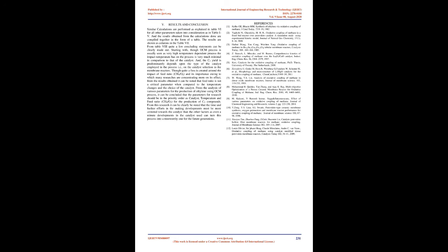Table 1, analysis table for membrane reactor at normal varying temperatures. For statistical analysis calculations, the factorial design technique is now applied on tables 1 to 5 to find the percentage weightage of the parameter impact on the OCM process. Table 6 gives the sample calculations for the C2 yield, Y, analysis in the membrane reactor. Here, the catalyst is considered as factor A, temperature as factor B, and AB taken as the interaction effect. The data at various catalysts and at specified temperatures are indexed as i and j.